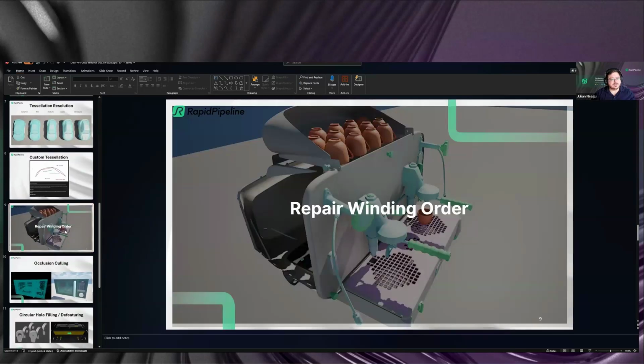We have a quite general, case-agnostic winding order correction. If I'm not mistaken, Unreal tries to correct normals and winding order as well on import for CAD files, but we have an option which operates with a raycaster, so it is independent of lots of particular issues with certain file formats or certain tessellation problems. So just activating that on import, or with an additional preset, to go over any mesh which has winding order problems usually fixes the issue and orients the actual faces in the correct way.